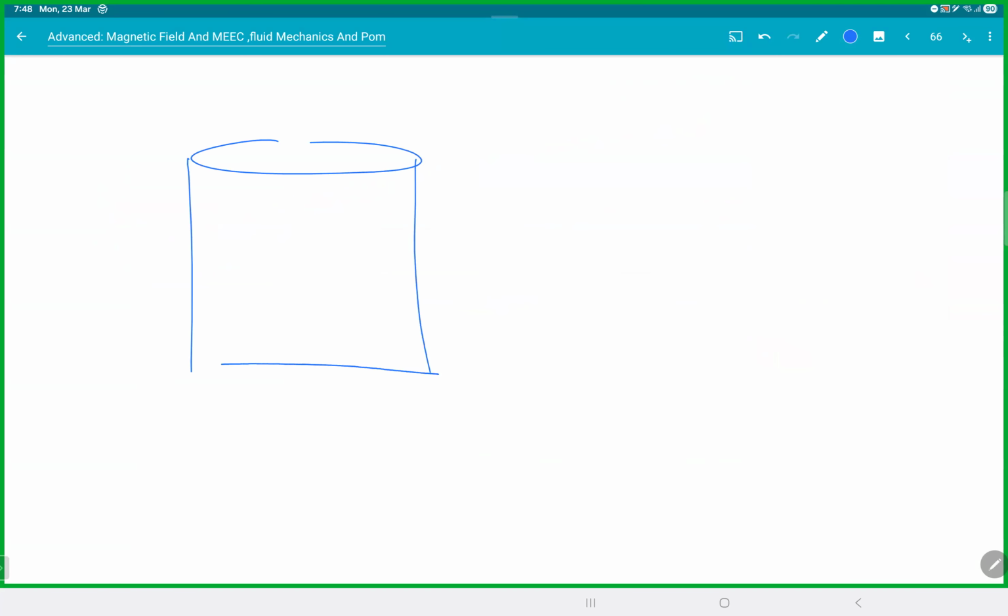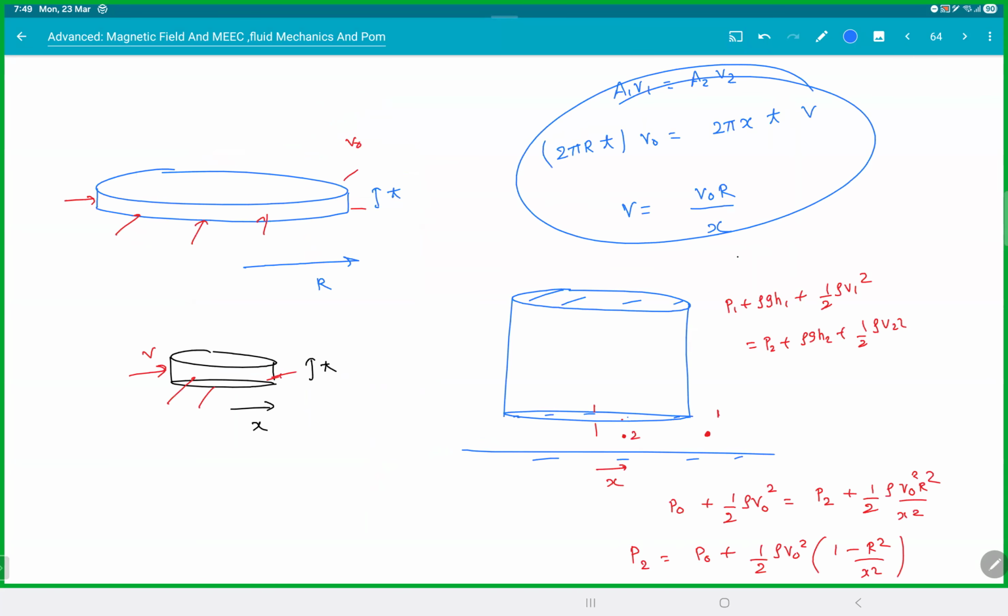So this is one way they can play around with equation of continuity and viscosity. So from above, P naught into pi r square. This will be mg and this would be P2 into 2 pi x dx. Integral will go from A to R. That's the pressure from the bottom. Clear with this? And that's the tension there. You'll get the tension from here. So the main thing is equation of continuity and Bernoulli. That was the whole idea there. All clear with this?